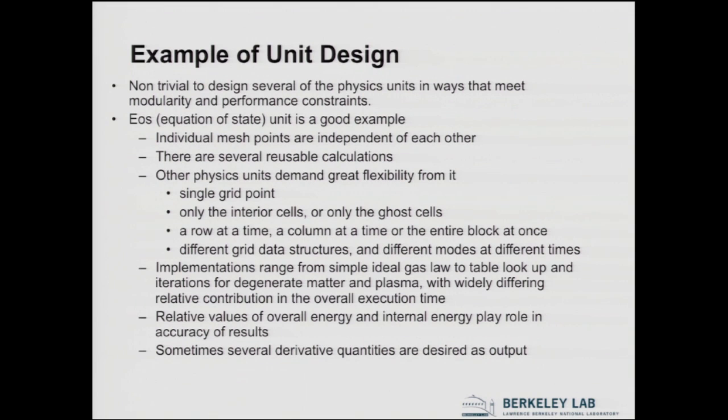So there are times when you're given certain physical quantities and you want to generate other quantities using it. And there are times when you do not even want to do it on specific discretized points. When you're initializing, for example, if you've initialized your domain with an ambient pressure value, an ambient temperature value, and density, and you just want to fill the rest of the variables, you just want the value. You do not want that value at a specific point.